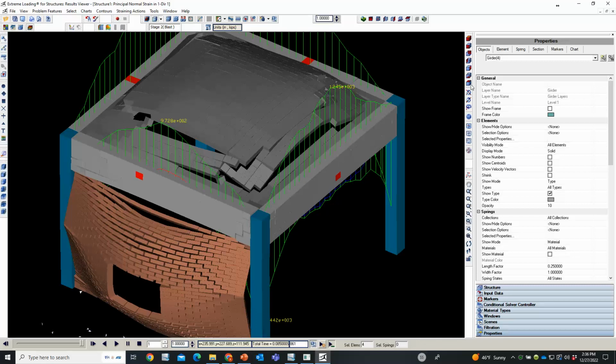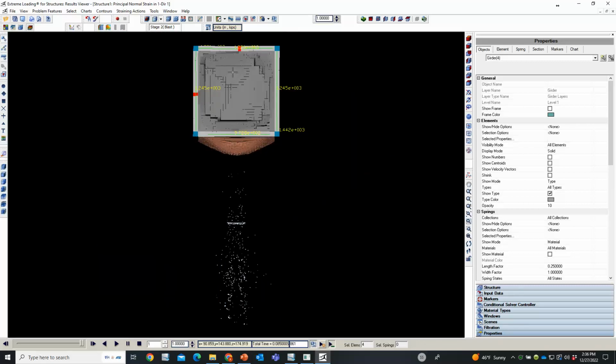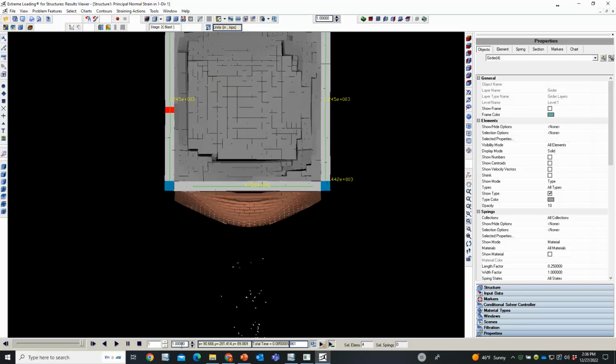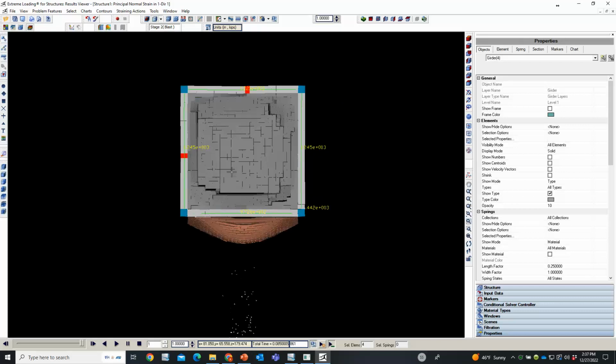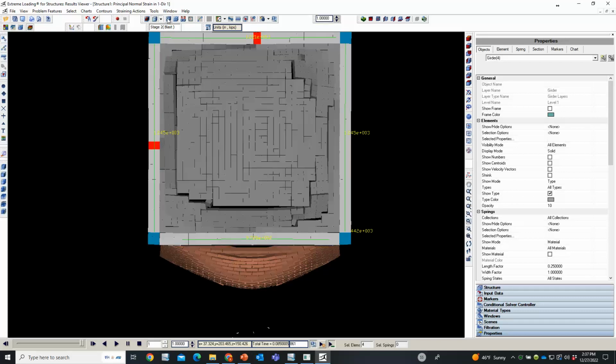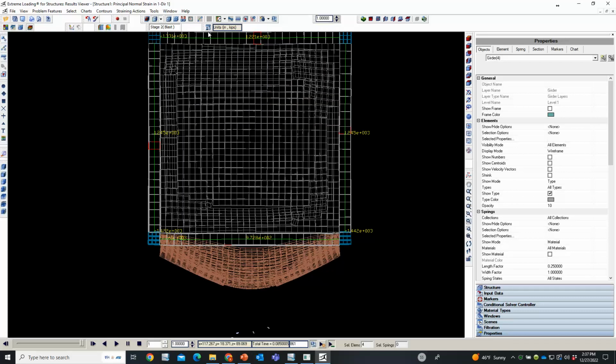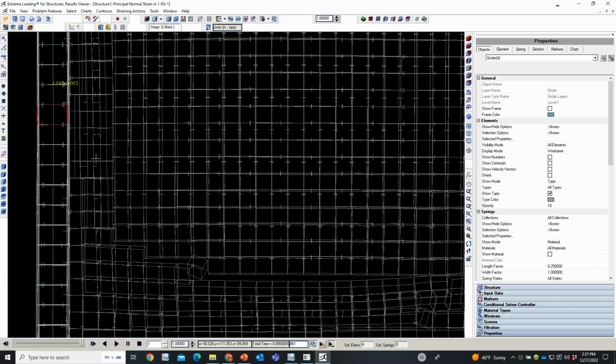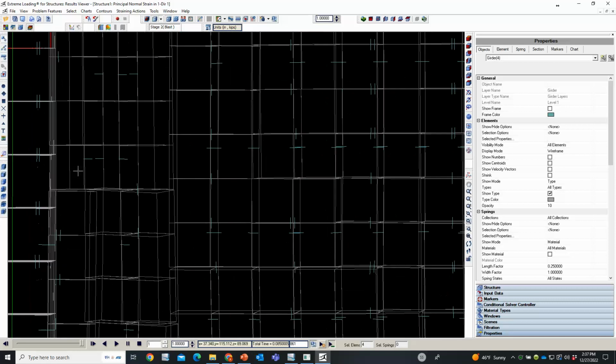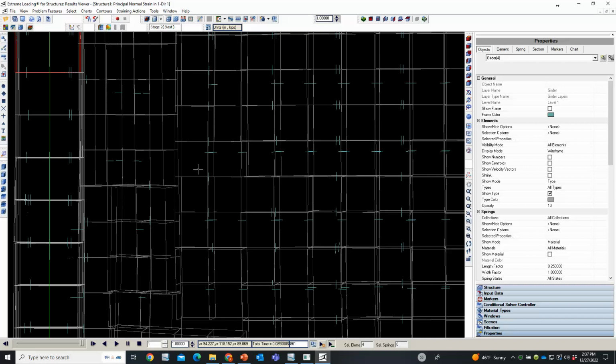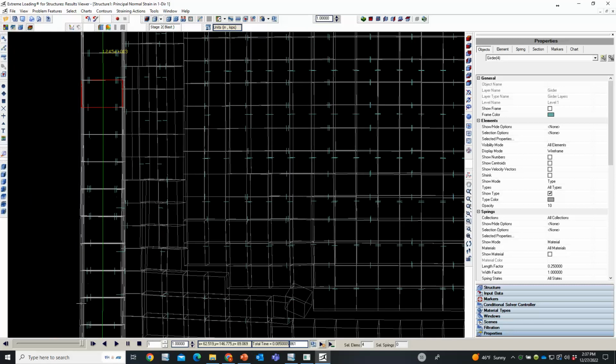And now let's bring a plan view because we need to see what's happening in the slab. So I need to view the slab in a wireframe mode, then show here the yielded springs. All the springs that you see, or all the lines, the blue lines that we can see in here, all of these are springs or reinforcement rebars that are yielded.